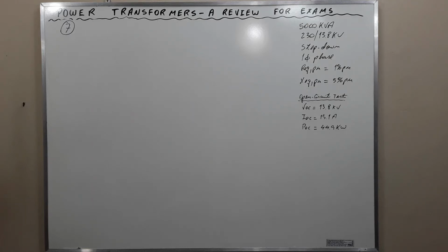The open circuit test performed on the low voltage side yielded the following data: VOC 13.8 kV, IOC 15.1 amperes, POC 44.9 kilowatts.